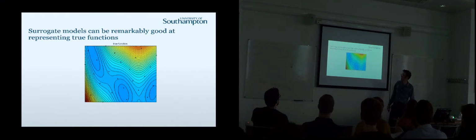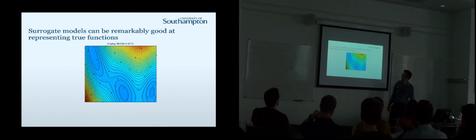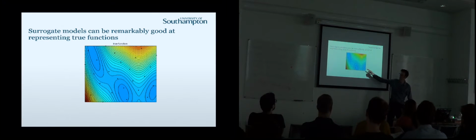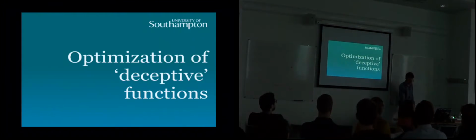And it looks really, really similar. So with Kriging, you might as well use that based on 20 evaluations rather than resort to the true function, which could take you days to calculate. Imagine if you had to crash a car to work out the characteristics of the crashworthiness of that car every time. You'd be better off crashing 20 cars and building that than resorting to running your optimizer on this. So that's the basics of surrogate modeling.